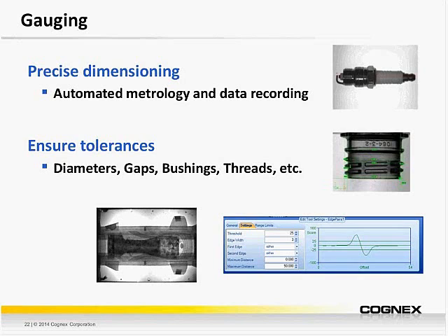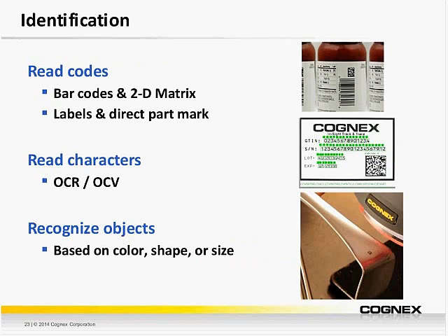If you want a pass-fail output based on these calculations, you can configure the vision system to determine if the dimensions are within tolerance. In this type of configuration, if the dimensions fall outside of spec, the vision system sends a fail signal to a controller, which triggers a reject mechanism to eject the product from the line. Because vision systems measure part features within 1,000th of an inch, they are suitable for a number of applications traditionally handled by contact gauging.